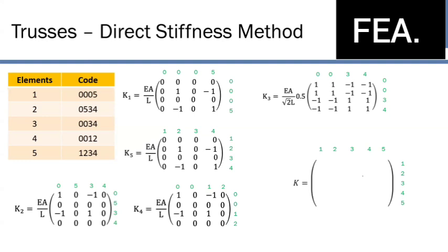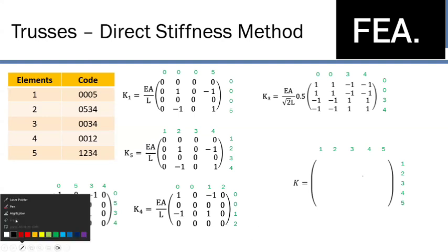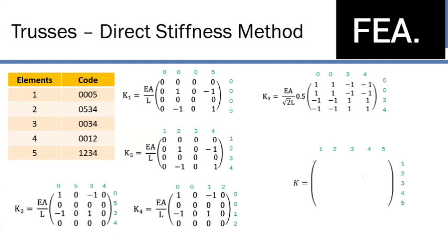It's going to be pretty menial when we do it by hand, but finite element analysis software will make it much easier. It's also pretty important for us to know the theory, so let's go through it together. Our first term in this global stiffness matrix is going to be this one term right here. So we look across all of our matrices and see if a 1 shows up, and where it shows up.